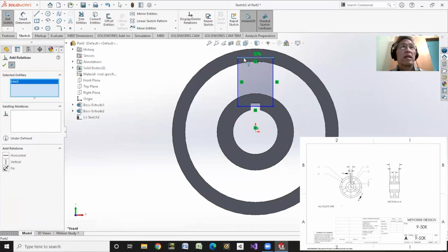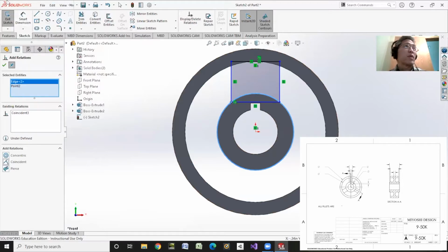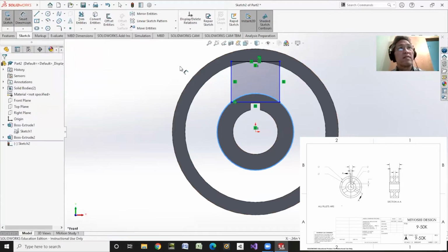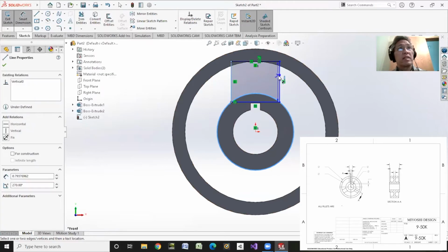I will this line and that circle, forget the face, and I want them to be tangent. I don't want that on the bottom. Instead, I want this point and that circle to be coincident. Okay? Obviously, they're the wrong width there. Well, not obviously, but it made the width off from what I want. So I'll grab smart dimension, and I'll just go from edge to edge.